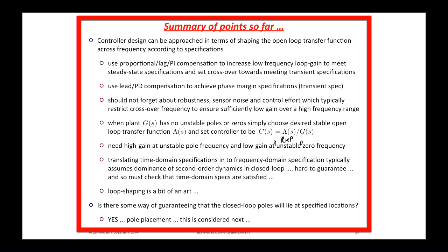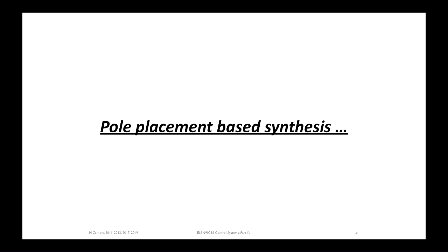And the main pitfall associated with pole placement methods is that the closed loop response is not just a function of the poles, it's a function of the closed loop zeros. So if you put all your attention on the closed loop poles, you're not looking at the whole picture. Okay, so while it seems like an appealing method, it's actually hard to use. All right, we'll look at that. That'll be the last thing we look at. Then we'll look at problem set 5, and then maybe look at an exam, and then we'll be at the end of the semester.